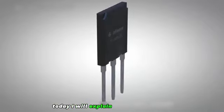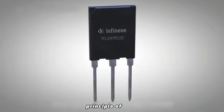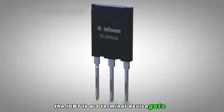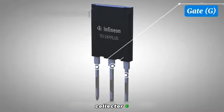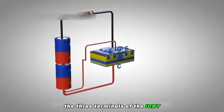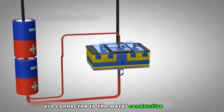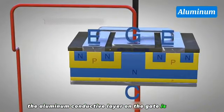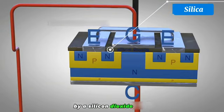Today, I will explain to you the working principle of IGBT. The IGBT is a three-terminal device: gate (G), collector (C), and emitter (E). The three terminals of the IGBT are connected to a metal conductive layer, usually made of aluminum. The aluminum conductive layer on the gate is insulated by a silicon dioxide layer.